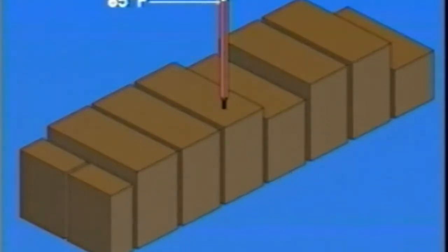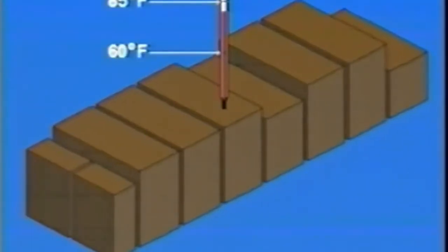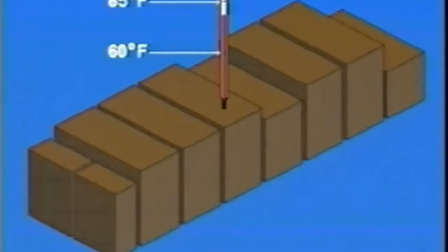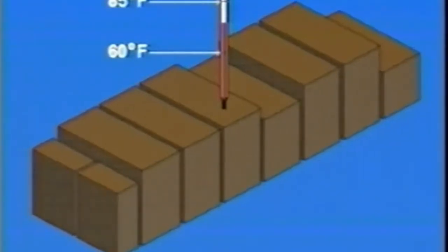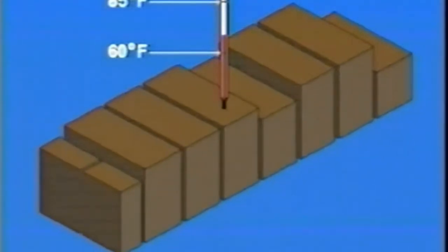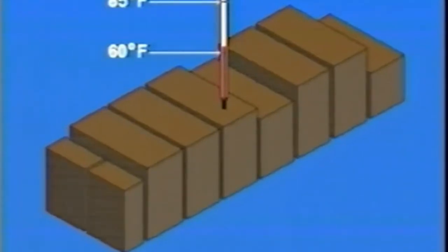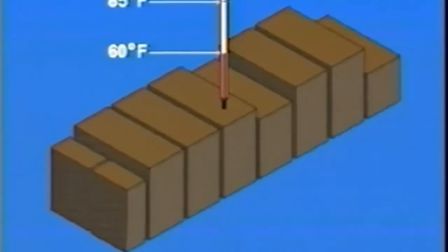To be able to find the weight of the oil, you start by reducing the measured volumes to a standard temperature of 60 degrees Fahrenheit, or 15 degrees centigrade. So, a volume measured at 85 degrees Fahrenheit must be reduced to a net volume at 60 degrees Fahrenheit. To do this, we use the reduction tables, the so-called ASTM tables. We will return to this in a moment. Your immediate problem now is to find the accurate temperature in each tank.